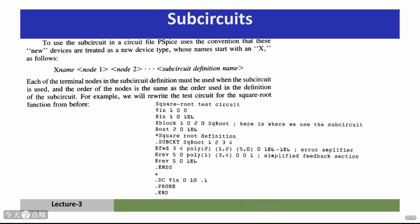In the example, Xblock 1 0 2 0 SQ root connects the external circuit's node 1 to the subcircuit's input node 1 and node 0, ground, to the subcircuit's input node 2. Similarly, it connects the subcircuit's output node 3 to the external node 2 and output node 4 to external node 0. The subcircuit definition is placed somewhere between the title line and the .END statement. You can even put these definitions in separate library files and load them using the .LIB command.